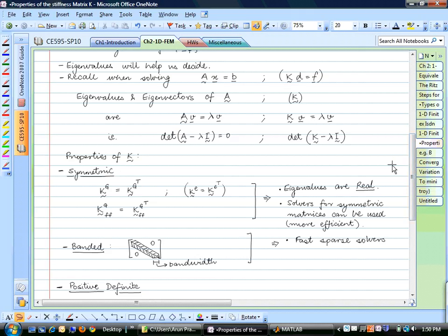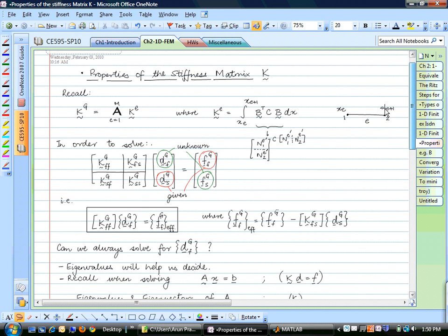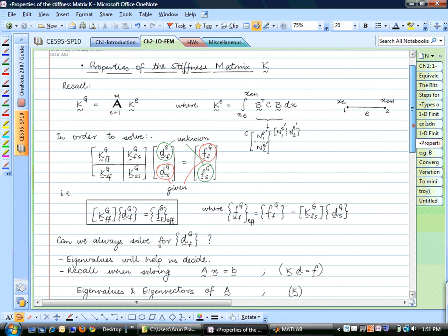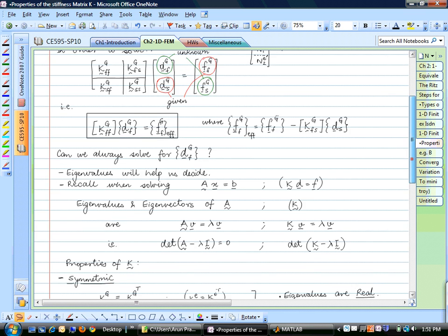We said that our element stiffness matrix was going to be symmetric, right? That is straight away from the first line right here. So this is the same vector multiplied by another vector transpose. And actually, what you can do is take this constant c, the scalar, to the left-hand side, and what you're left with is this. So this is a 2 cross 1 multiplied by a 1 cross 2. This will give you a 2 cross 2, which is symmetric.